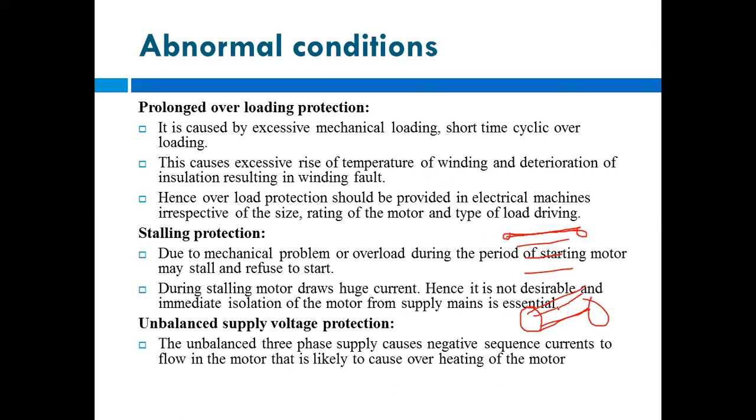So why is this? Because this motor has a tendency to stop the starting. Because they get interlocked, the stator teeth and the rotor teeth get interlocked here, so that they refuse to start.